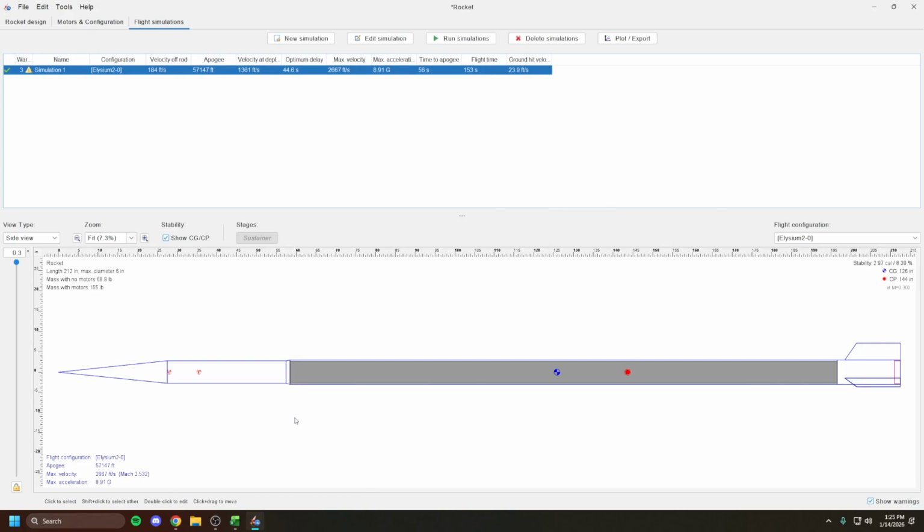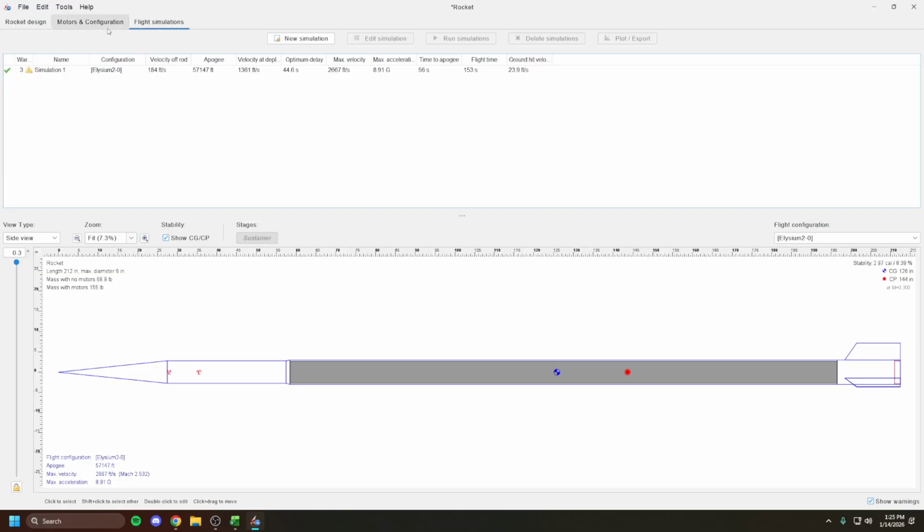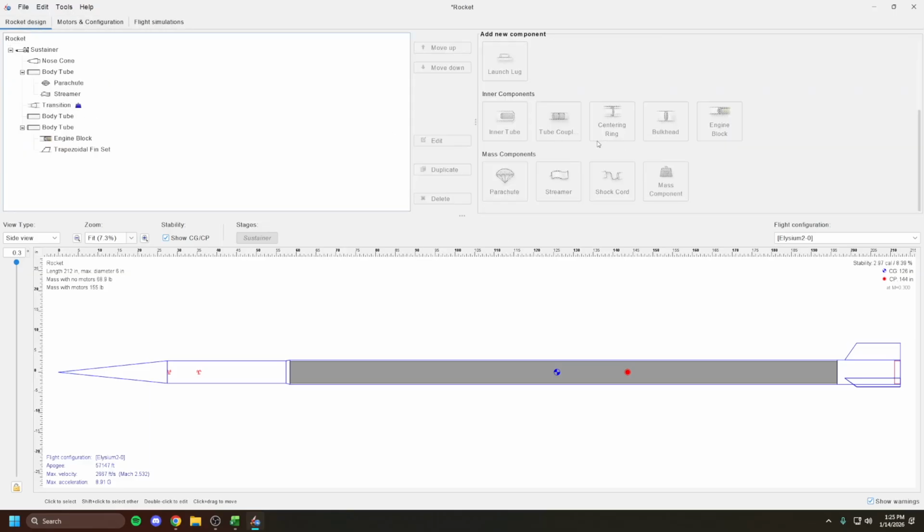Okay. So that's everything I think you need to know about OpenRocket. It's very useful to have a spreadsheet of all the actual masses of your components. Make sure that everything is accounted for, because when you build it and you're 5 inches off on your center of gravity, they're going to be looking at you to figure out why. So that's what I can say. Make sure to save it. Nothing saves automatically. That's all I got for you.